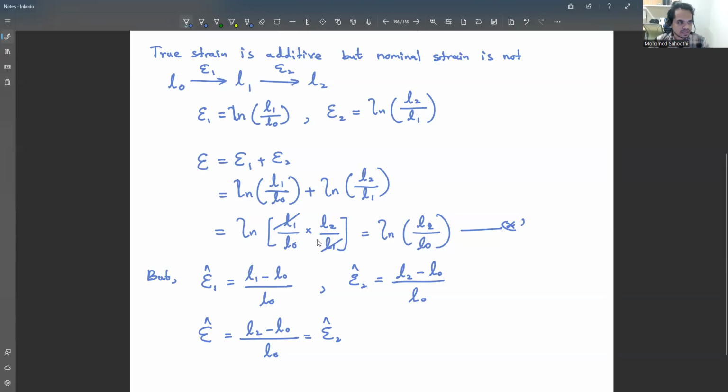But the true strain is additive. That is why in finite element software like Abaqus, we use the true stress and true strain, because it is additive. It is easily applied for numerical applications, right? I think this video is a bit extended, no issue, but we have discussed a lot of important stuff.